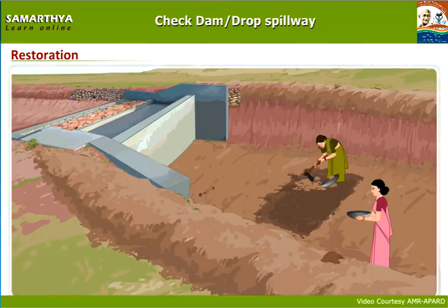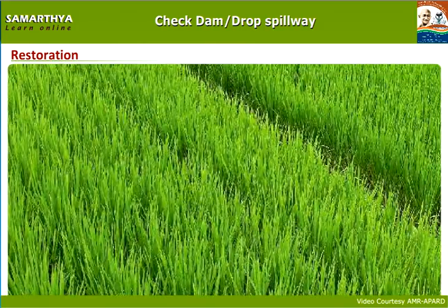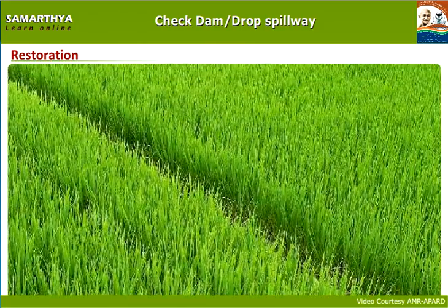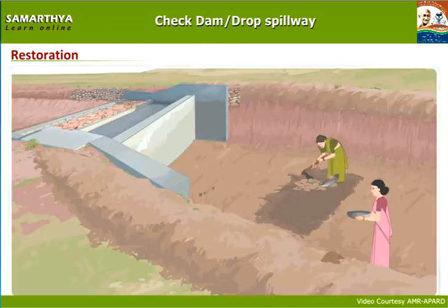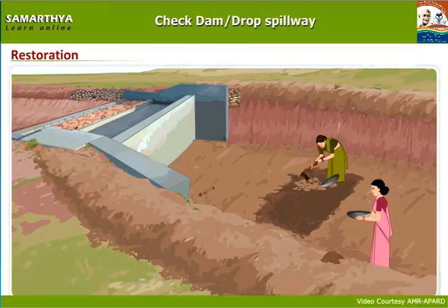This silt can be moved to crop farms to increase fertility to attain high yields. While removing silt from the water catchment area, remove it 1 meter away from the end of upstream side wall. If it is removed close to the wall, walls of check dam get damaged.